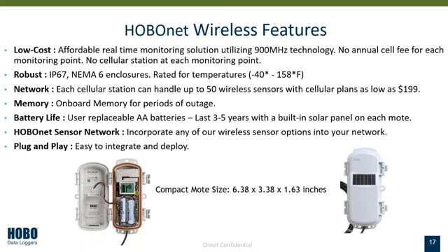So again, some of the biggest features of this wireless sensor network are, number one, it's low in cost, right? So you have this affordable real-time monitoring solution. It's utilizing that radio communication, so there's no cell fee for each individual monitoring point. The motes don't have cell built into them. They have radio. You don't have to pay a cell fee for those individual monitoring points. And it's typically more affordable to do a wireless sensor setup than it would be to buy a whole station as well. So it's the upfront cost and the recurring cost year over year that you're saving.